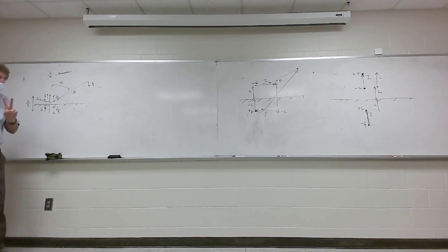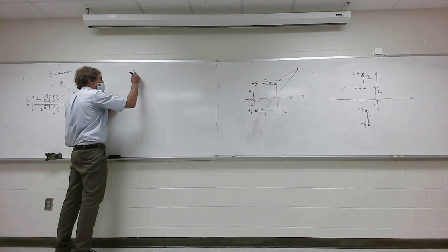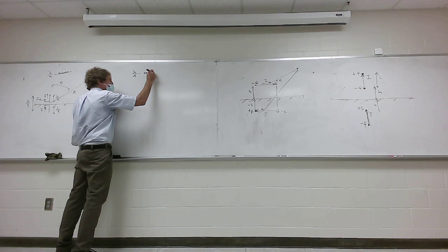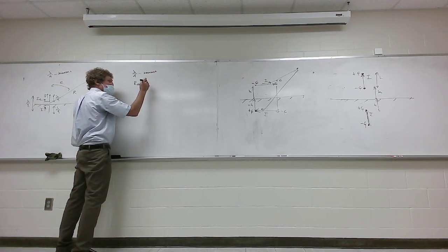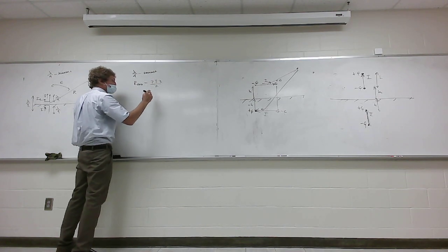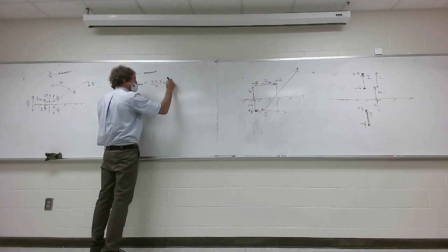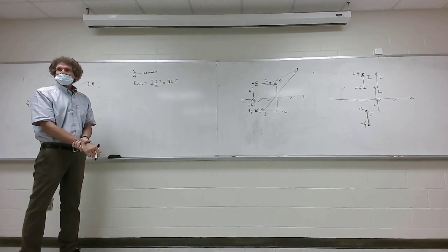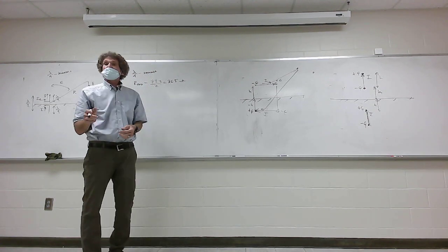Do y'all follow me? So, if you have a quarter-wave monopole, then R rad is really 73.2 over 2, which is about 36, I think it's 36.5, something like that. You can check that. It's going to have about 36.5 ohms. Now, that's useful information.